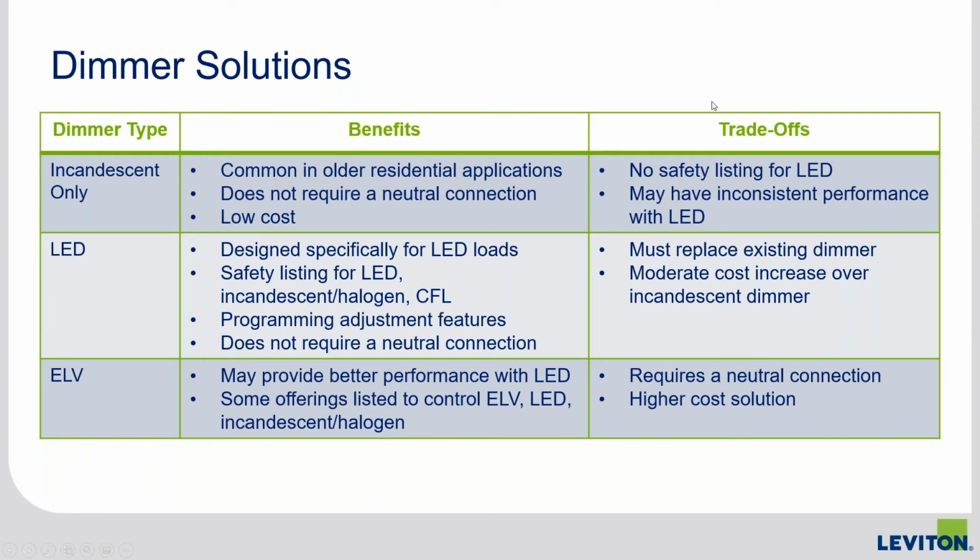Looking into these specifically, I mentioned some of these before, but I'll just briefly touch on them. Incandescent controls, since they were so simple, were very inexpensive. They did not cost that much to manufacture, and they weren't listed for LEDs. They weren't designed for LEDs. So using incandescent-only controls with LEDs is not only a safety issue, it's also a violation of the NEC code. Aside from that, you're more than likely going to have performance issues that are going to result in problems.